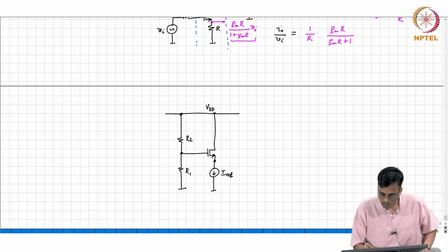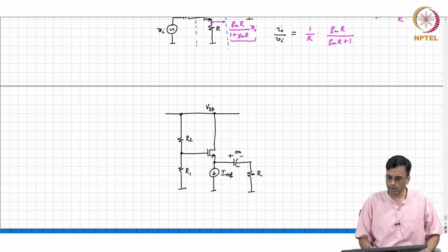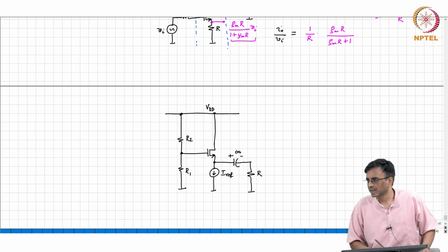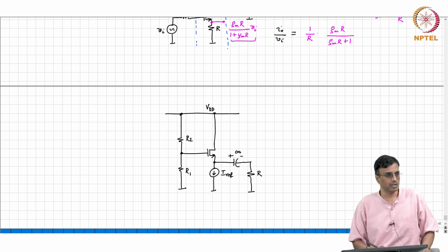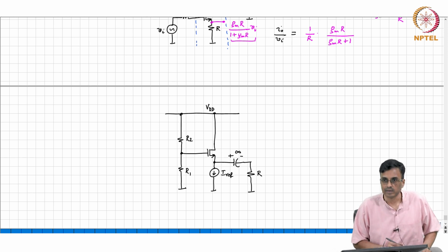Okay, one suggestion is to do this through a capacitor. And why do we need the infinite capacitor? So that we don't mess with the operating point. An alternative would have been to remove the Iref and put the R there itself. So R not only appears in the small signal picture, but also appears in the quiescent operating point. Okay, all right. Then what else?